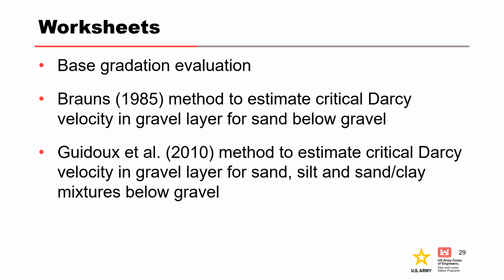The second worksheet is for the Bronze 1985 methodology to estimate critical Darcy velocity in a gravel layer for a sand below gravel. And the third worksheet is for the Guido et al. 2010 methodology to estimate critical Darcy velocity in gravel layer for a sand, silt, or sand-clay mixture below gravel.